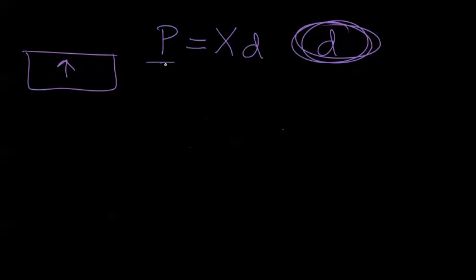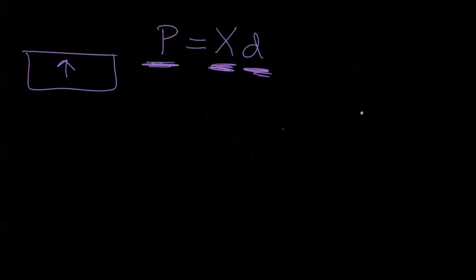So we have polarization equal to the stress times the piezoelectric d constant. The easy way to get a feeling for this is that we apply a stress, and this piezoelectric d constant tells us how much polarization we have. The units of polarization are coulombs per meter squared.